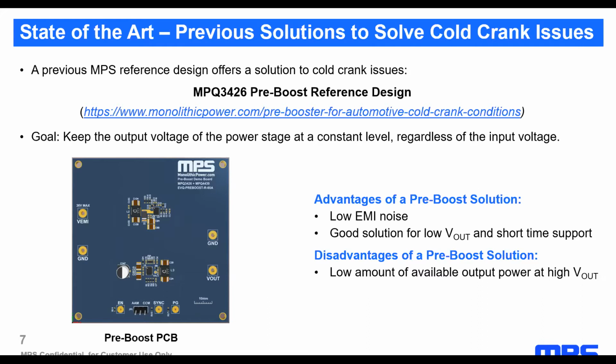The boost converter will boost the battery during cold crank in order to acquire a stable voltage. Apart from this, the pre-boost will act also as an EMI filter, so we get low EMI noise. But there's a limitation, that is that at high output voltages, there's a low amount of available output power. So this design is not suitable for ADAS.